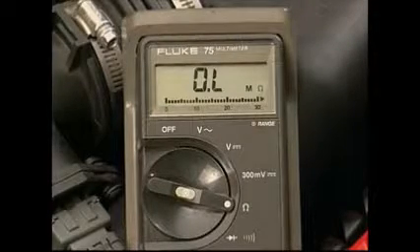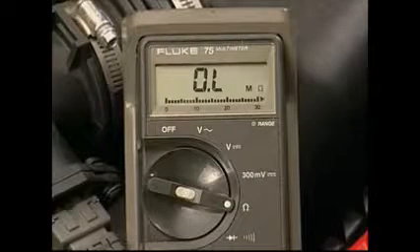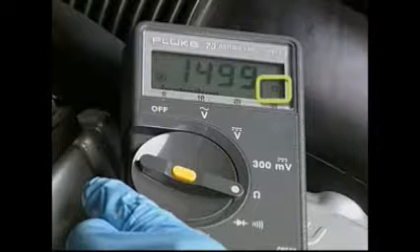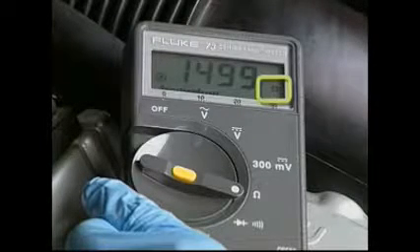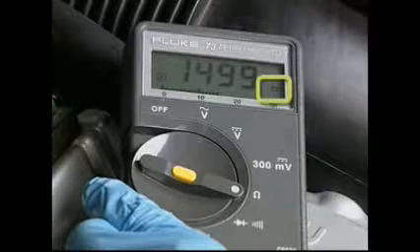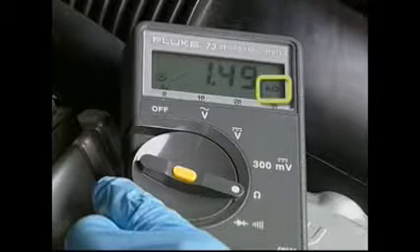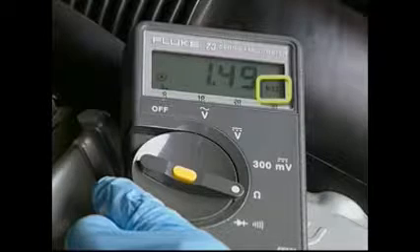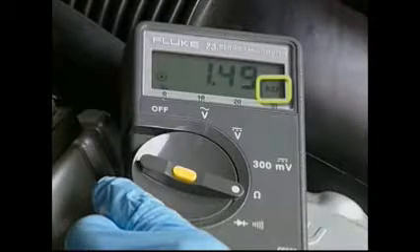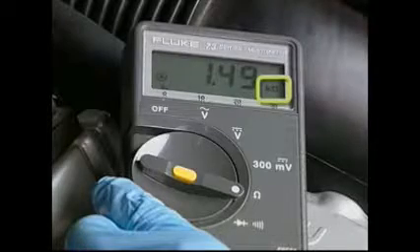If a resistance is measured that exceeds that range, the display will show OL or over limit. If you are using the auto range feature for automotive tests, the display will show either ohms for readings under 400 ohms or K ohms for readings between 400 ohms and 399 kilo ohms, 399,000 ohms.